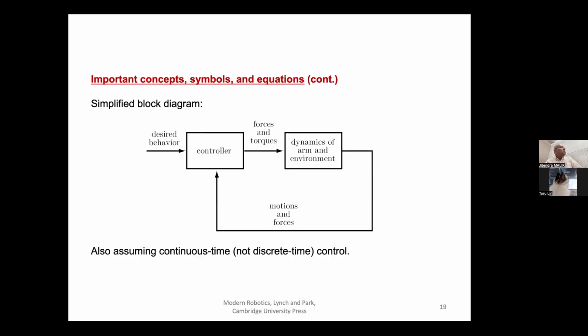And so what we do is we often abstract away the lower level stuff. In the lower level controller, we just say, okay, we trust the motor supplier or the robot manufacturer, and that the low level controllers will do sensible things. Hopefully they give you access to it. And typically the way you want access is because there'll be a low level PID controller. So you want to be able to tweak those Ks, the K sub P, the K sub I, K sub D. You need to be able to tweak those. So far, so good.